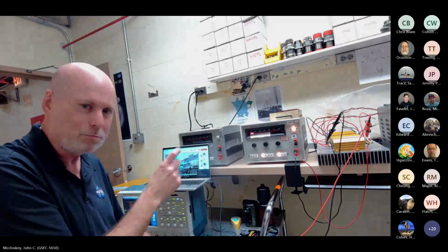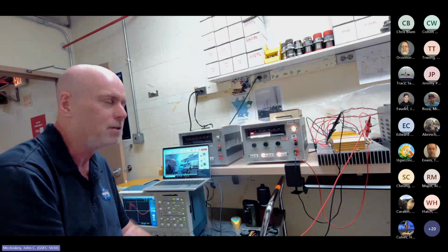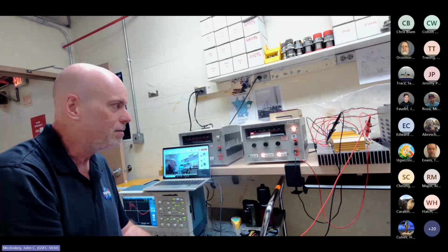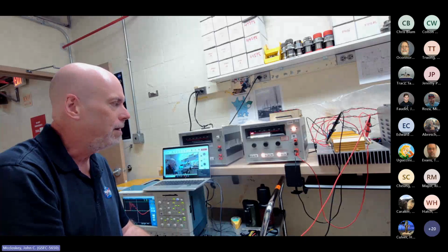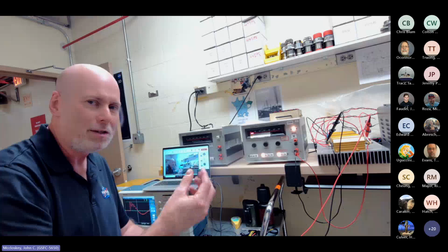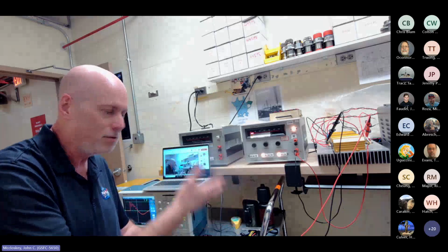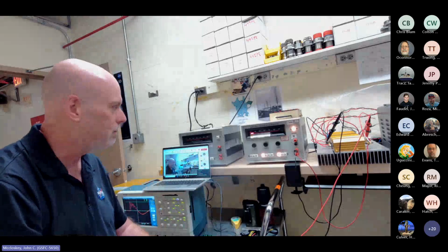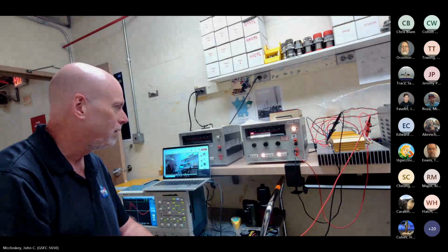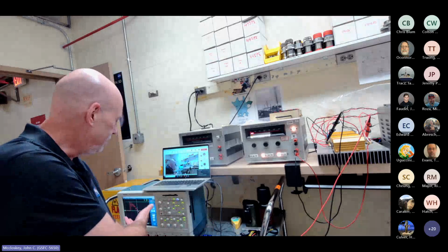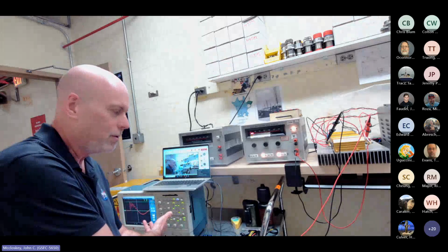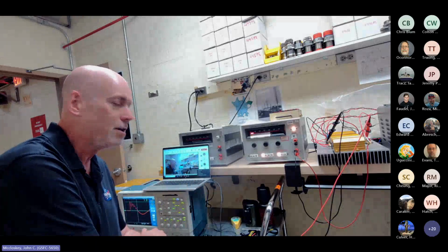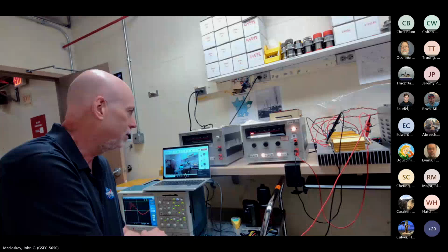But no, there's probably some inductance. We know there's some inductance. It's just how much. If it's a wire wound resistor, that inductance could be pretty significant. And then capacitance between windings and all that sort of stuff. So at higher frequencies, it's not just a 5 ohm resistor anymore. So all these things to pay attention to if you're seeing some strange things. When you're looking at a signal on the scope that doesn't look quite the way you expect it, it means you need to adjust your expectations. You need to adjust your model.